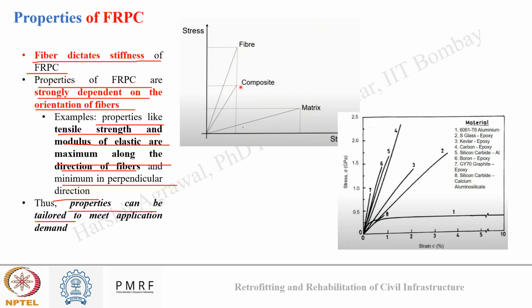We can see in the first diagram the justification of the statement we made initially when we talked about composites: in combination, a composite has superior performance than the individual components. Fiber has higher strength and higher stiffness, while matrix has lower strength and higher percentage elongation. A combination of both gives the composite decent strength as well as stiffness and elongation property.